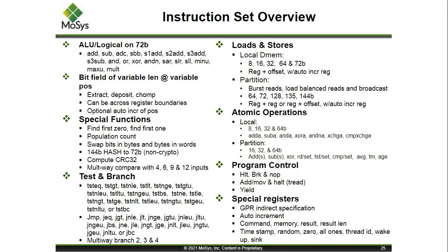Again, briefly, I'm going to show the instruction set. It's a rather robust instruction set. It has all the bit manipulation operations, some specialty functions like hash, and lots of test and branch and load and store instructions as well. As Gus mentioned earlier, the history of this comes from a MIPS background. The designers of these processors all had a MIPS history.